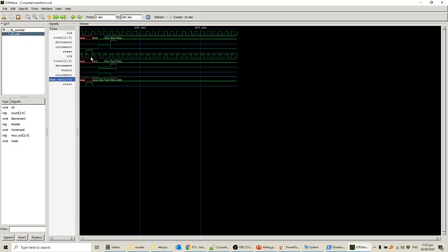Okay, so these waveforms are the main source which help us when things are stuck. If I don't get count correctly, then I'll go back to the design diagram and see from where count is coming. Count is coming from mux out, so I'll see whether mux out is correct or not, whether enable signal of register is coming correctly or not, and that will help me identify where the bug is. So that's it for the simulation and verification. I'll make another video for Vivado based simulation.